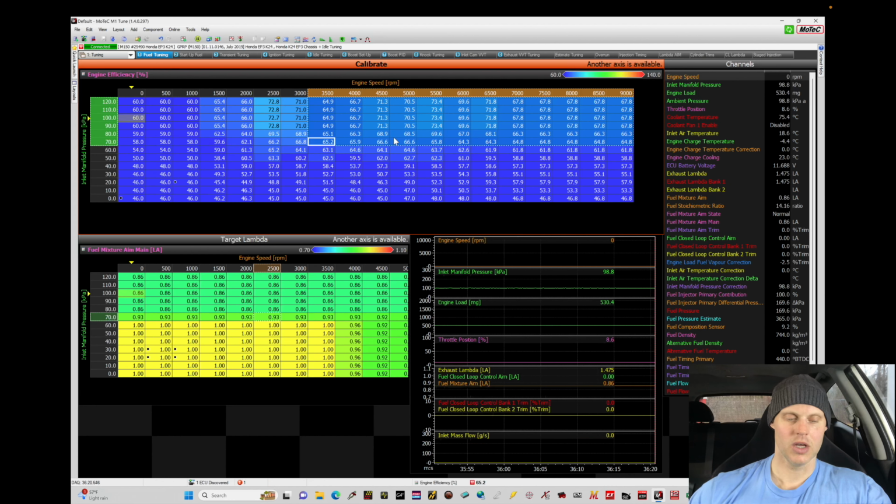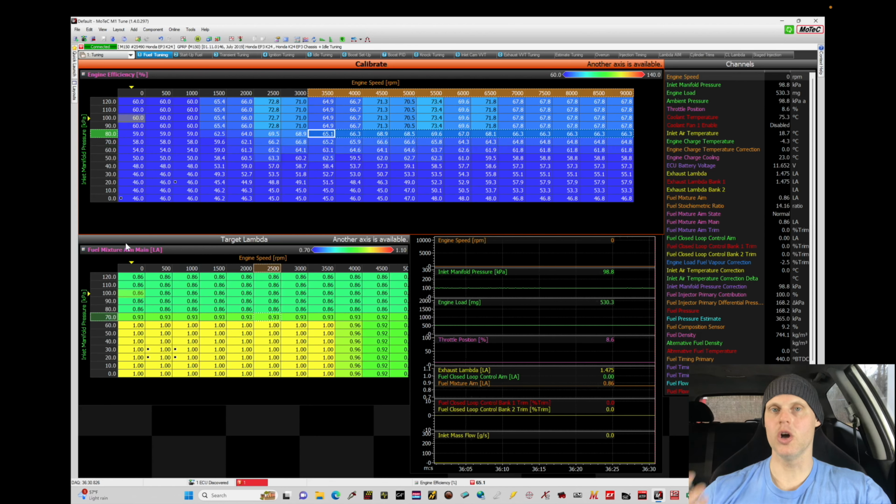We kind of have to draw some of the parameters, draw a line, so to speak, within the table. So we're going to say here 70 kPa and below, VTEC's off. 80 kPa and above, VTEC could be on or could be off depending on the load and the throttle angle. So let's look at this real quick.